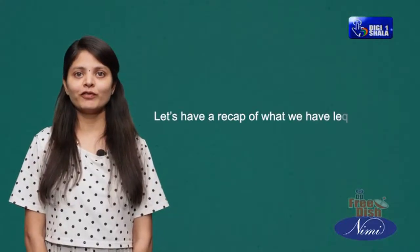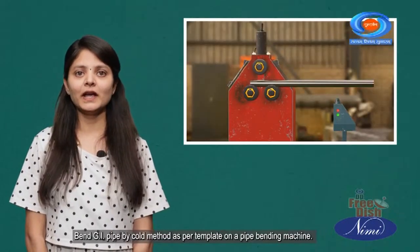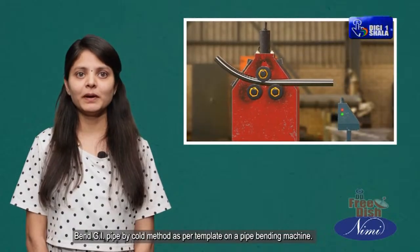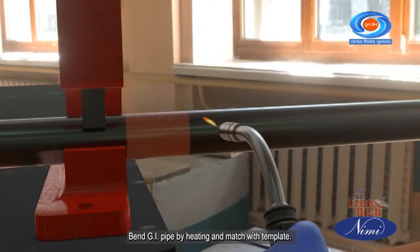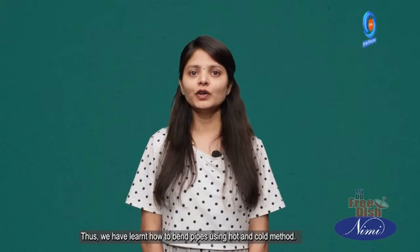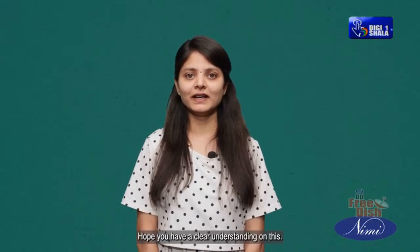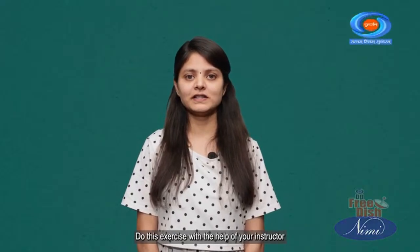Let's have a recap of what we have learned today. We have learned to bend GI pipe by cold method as per template on a pipe bending machine. Bend GI pipe by heating and match with template. Thus, we have learned how to bend pipes using hot and cold methods. Hope you have a clear understanding of this. Do this exercise with the help of your instructor.